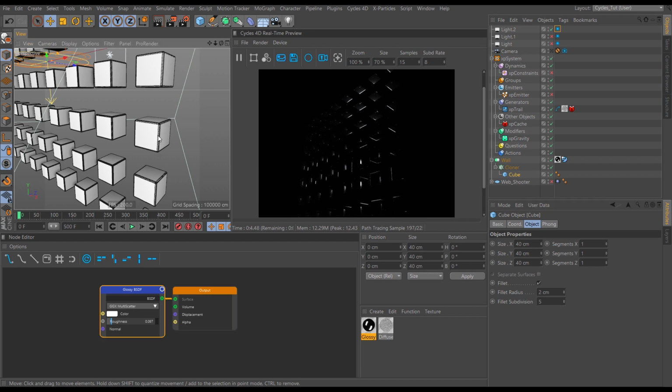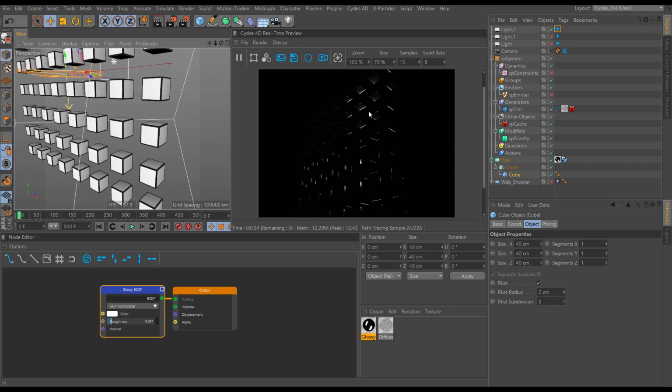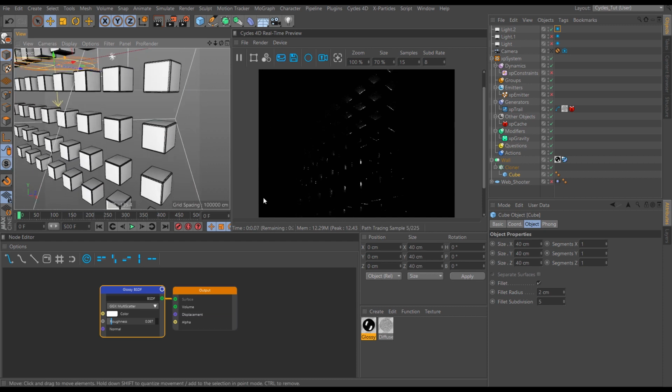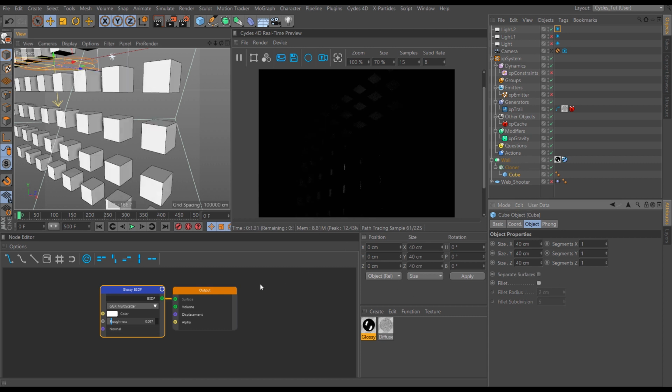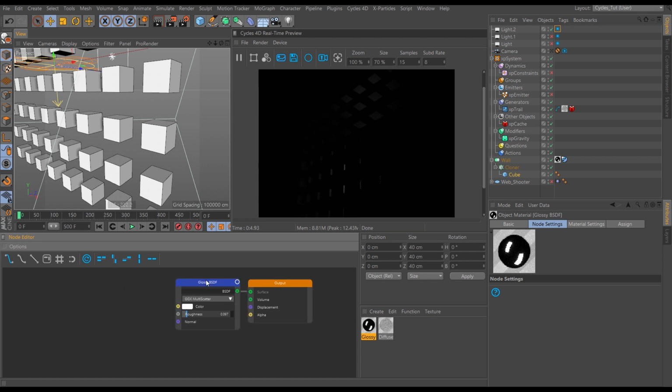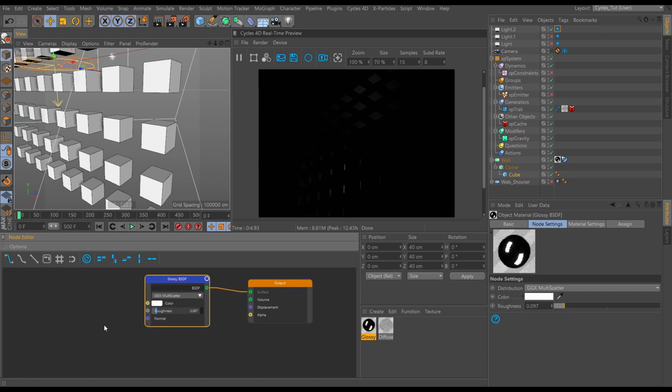But look how much more geometry. As soon as I put that fillet on, you can see these nice highlights bouncing off the corners now from that rear light that we've created. But this is creating loads more geometry that we probably don't need, so let's just take that fillet off, because if we go to our glossy material in Cycles, we're now able to do a bevel at render time, which is fantastic.